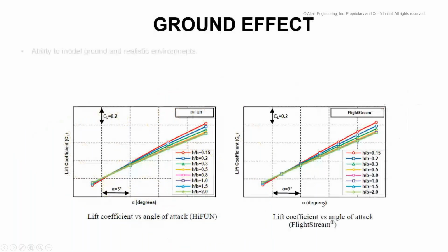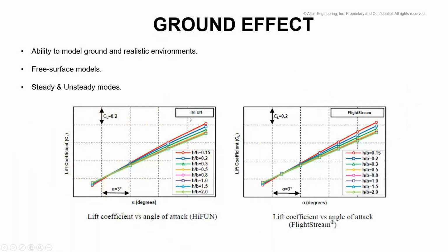So, talking about ground effects, Hyphon is another tool coming out of India, and here it's based on the finite volume method on unstructured meshes. You can see the comparison of the tool with the FlightStream results. So it can capture the ground effects very nicely, whether we are talking about steady or unsteady modes. Here, the comparison is made with the CL lift coefficients, and you can see the comparison with a band of angle of attack of 3 degrees.